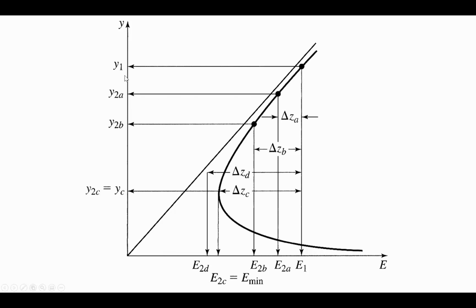And so that made the depth get lower because of the step. And if we had delta ZB, then the step up is even bigger, so that's extracting more specific energy, and so there's less available for this now downstream depth y2. And the critical step height, the delta ZC, is the step height that's associated with the critical depth and the minimum amount of specific energy for a certain flow rate before pooling occurs.